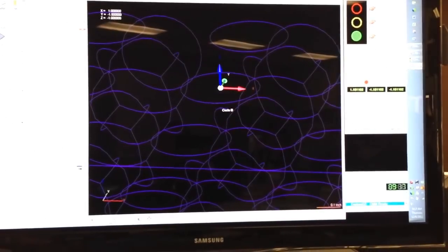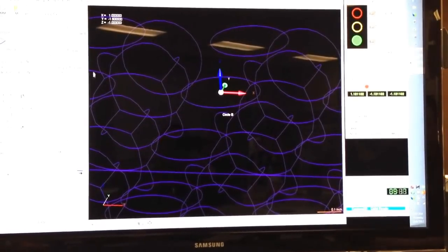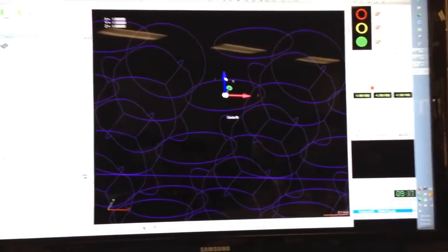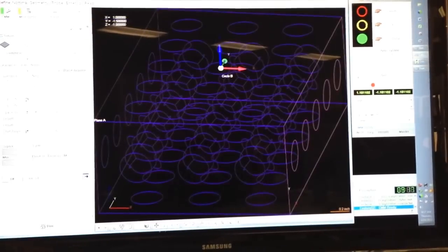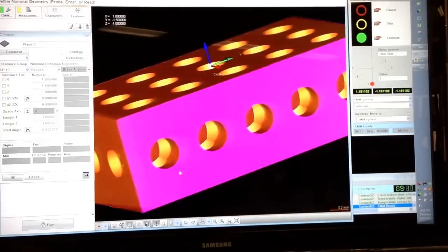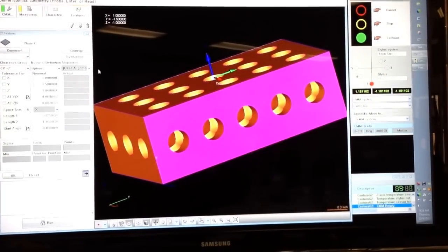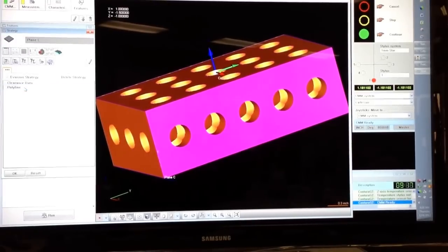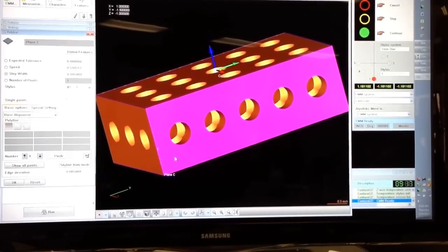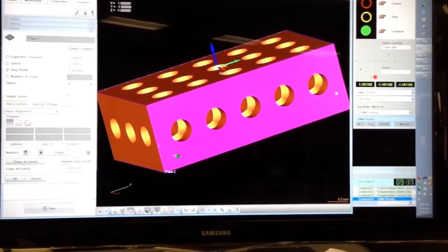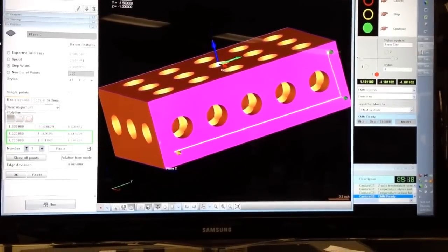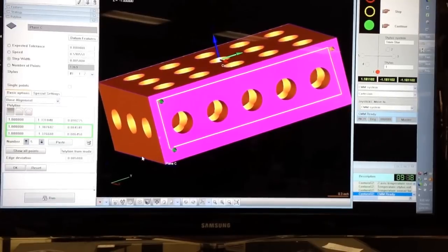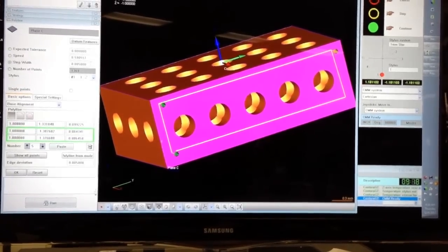Finally, we'll do plane number 3, or plane 2, which is going to be plane C. And again, we're going to put a polyline in here. Strategy, insert polyline. We'll open up this polyline, and we'll take that measurement. 1, 2, 3, 4, and 5 to make a nice box type pattern.